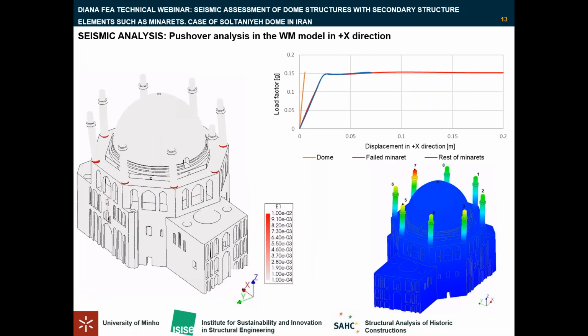To perform the seismic analysis, pushover analysis was conducted on the numerical models in both longitudinal, meaning X, and transversal, Y directions, considering positive and negative orientations. Pushover analysis is a nonlinear static analysis carried out under constant gravity loads and monotonically increasing horizontal loads.